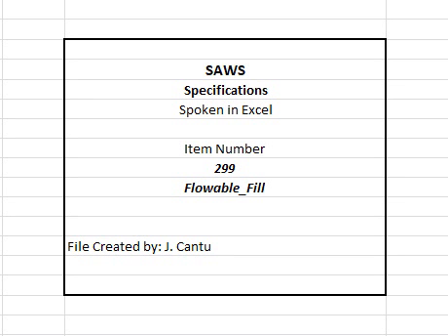Flowable fill is a concrete material suitable as a backfill for utility trenches, abandoned pipes, manholes and valves. It is a heavy material and will exert a high fluid pressure against any forms, embankment, or wall used to contain backfill.